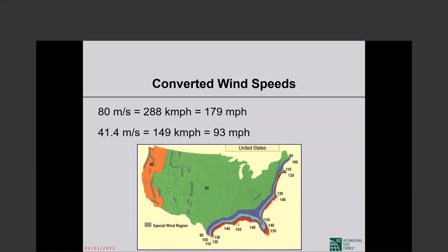And remember, always, pressure due to wind is proportional to the square of the velocity. So you go from 150 to 180, that is a sizable increase, but 150 squared to 180 squared is a much bigger increase. Okay, so I want you to appreciate that in parts of Bangladesh, you have to design for extremely high design wind speeds, which will give you very high design forces to deal with in your structure.